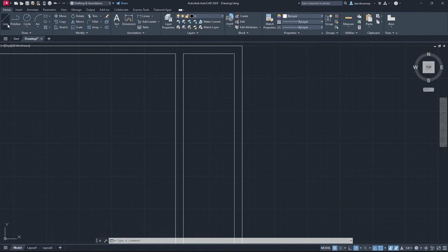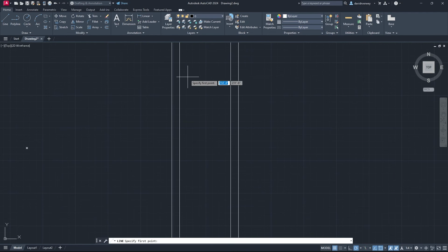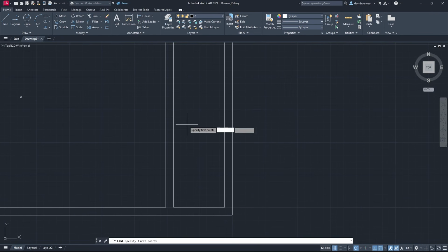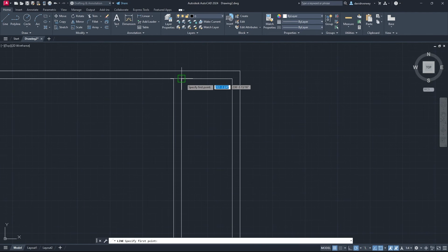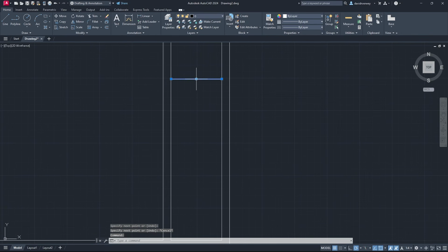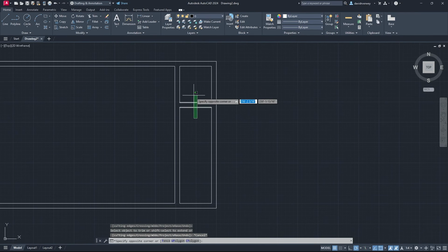And then we're going to have a section for our firm. We're going to have a section for the date. We're going to have a section for our drawing revision number. We're going to have the company and everything like that. So I'm just going to come here. I'm going to come down, draw a line there. I'm going to offset it, and it's going to be 1 foot. Offset that. And then I'm going to trim again. Again, I don't have to do it so complex, but I'm going to anyways.